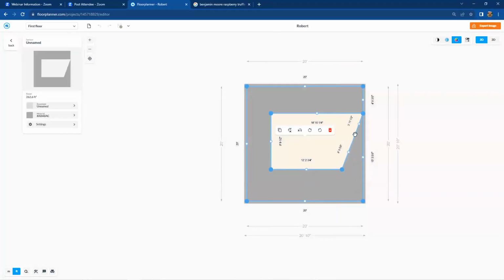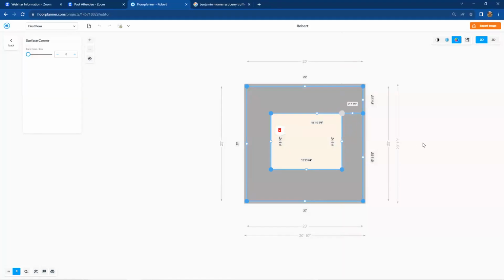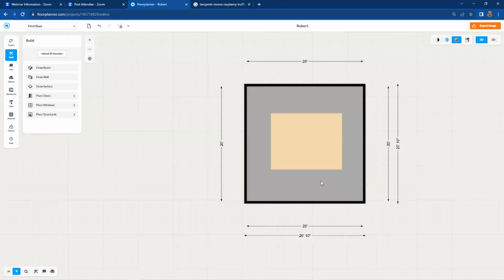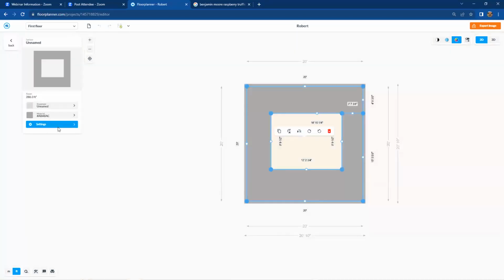And one more point right here. So let's say that's your tray shape with a hole in the center. I can select that volume, go to its settings, raise from floor, raise it up 8 feet. That's a 10-foot high ceiling, just 8 feet. And then I'm going to give the thickness to that tray as 2 feet to finish out the rest of the space.